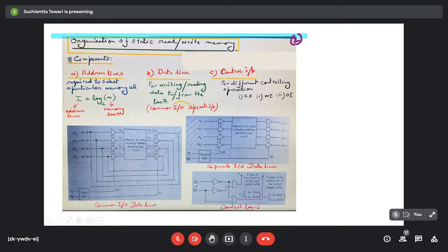Here, when we want to select that particular memory cell, we have to give the signal 0 here. Why? Because chip select is active low. Fine, here we are giving 0. That means this chip is selected. And suppose we want to perform the write operation. If we want to perform the write operation, we have to give 0 here. So here it becomes 1, here it becomes 1, and here it becomes 0 and here it becomes 1. So the output of this particular AND gate would be 0 because one of the inputs is 0. And here the output of this AND gate would be 1.